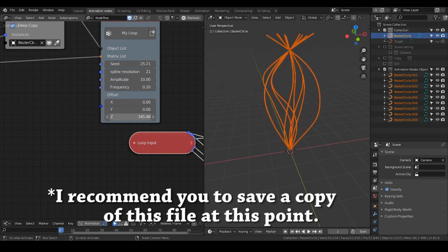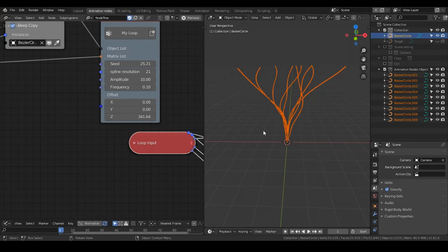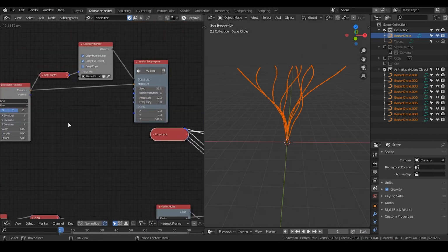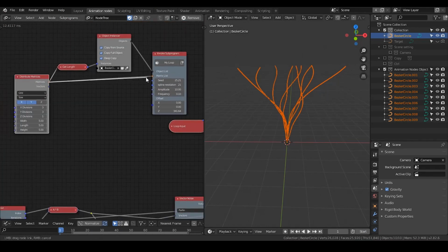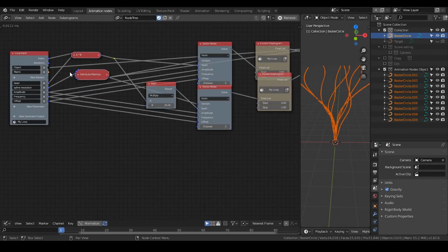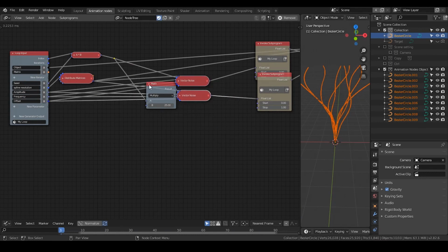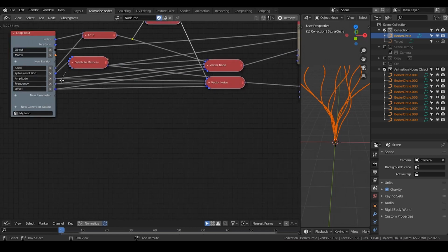I think this tutorial can already be done. I think this is already something completely interesting to see. Our end goal is to assign these 9 different splines to 9 different locations, and that's why we are putting 9 different matrices into this matrix list. And now this is the moment we are going to use this matrix list. Firstly, let's organize this tree better so that we can see things more clearly. Let's just collapse all these meaningless values. I'm going to shift right mouse to add a reroute.